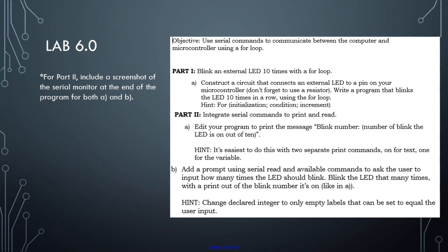I would recommend blinking the integrated LED first. I think I talked about this last week, so it's always good to use the integrated components if you can first to check that your code works as a verification, and then you can connect your external components and make sure those are connected right. So if it works right the first time using the integrated LED and it's not working when you have an external LED connected through your breadboard, then you know something is wrong with your LED circuit.